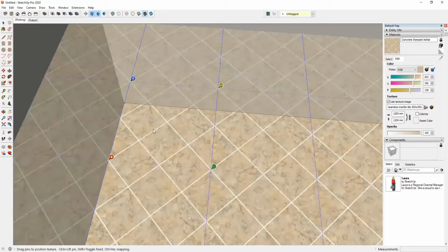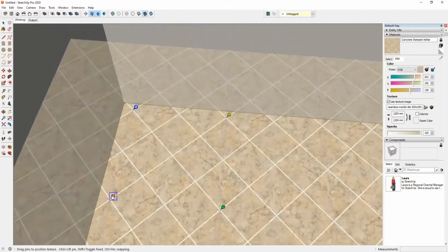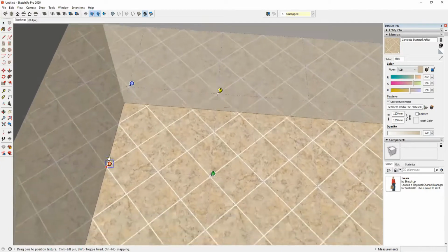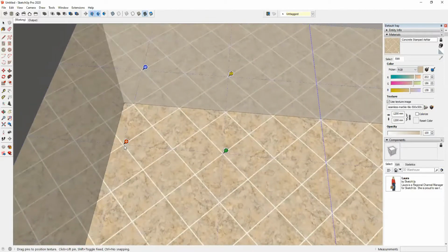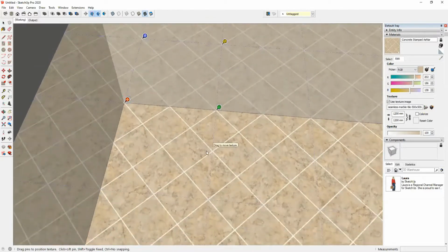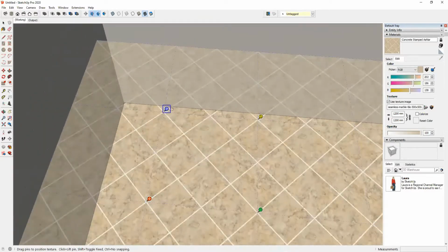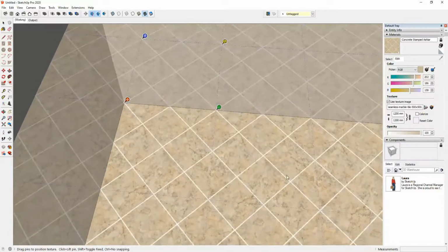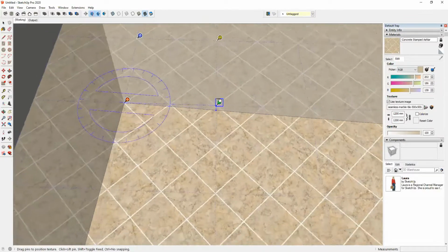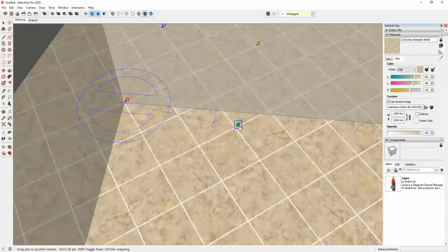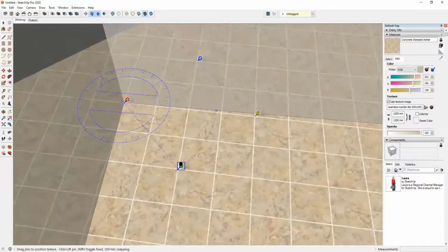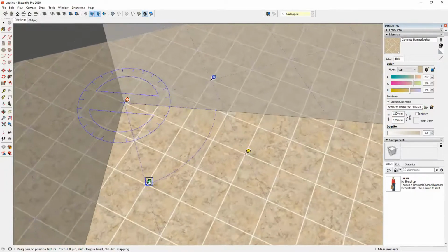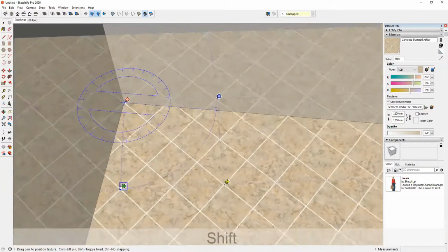Here under Position, this is for the move option. I can move it so that this corner is at the corner of the room, right? That's because this is the image, right? So make sure that the image also has the corner at the right point. Only then can you place it at the corner, and done. Now you can also rotate and scale together, and if you want to rotate only, then you can follow the guide for rotation.